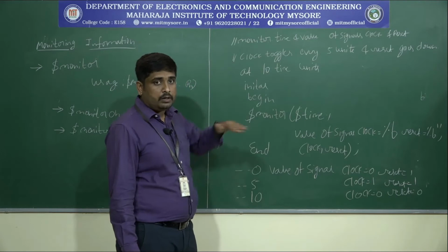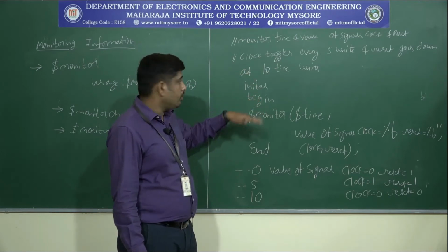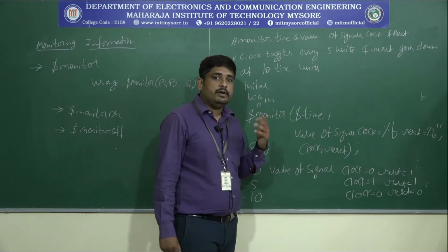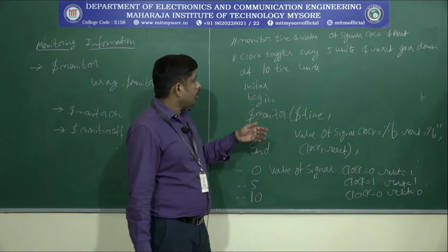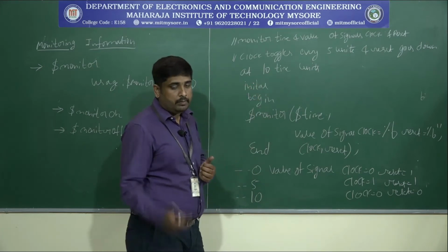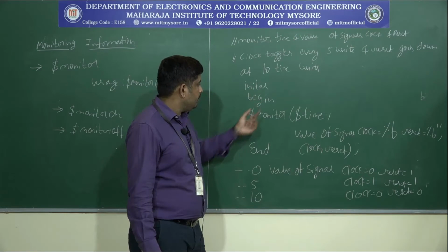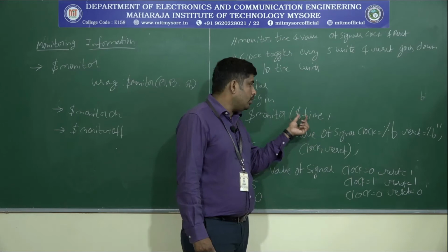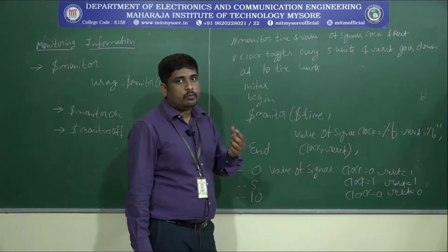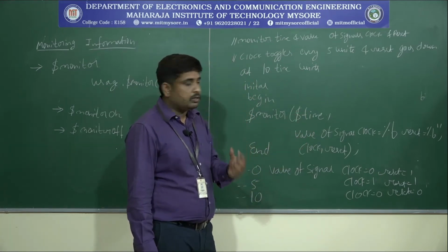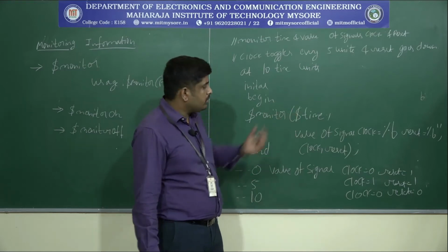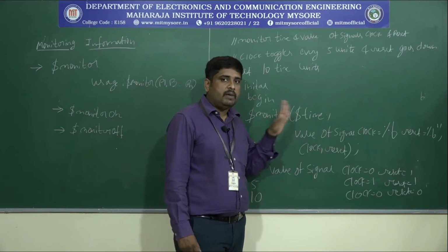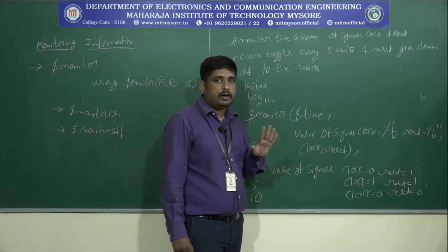So we have to write this using $monitor. Before starting $monitor, first we have to initialize it. The keyword here is initial begin, then $monitor, then $time. We already discussed $time: it indicates we have to calculate the current simulation time. You could simply write time, but then we can't calculate the current simulation time.